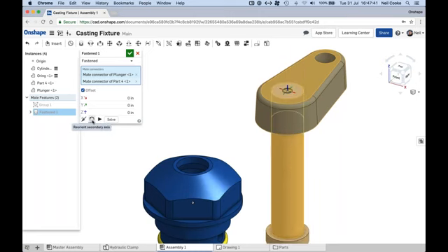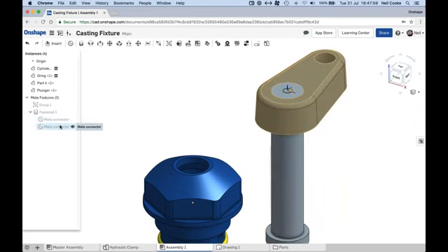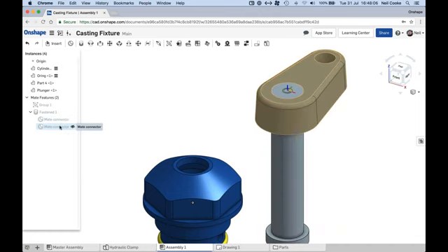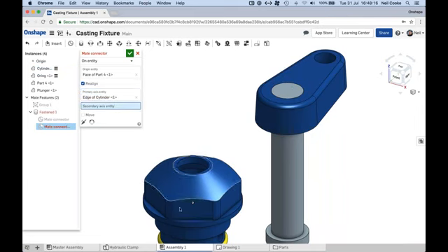The other things you can do here is you can flip it the opposite way around. You can also clock it around 90 degrees as well. The actual plunger is rotating there, which is why you can't see it moving, but you can see the mate connectors moving relative to each other. Another way to do it is if you expand a mate, you can see that it will actually show you the mate connectors that were used to generate this mate. So you can see the one that belongs to the plunger and the one that belongs to the mate connector. So if you wanted to put an offset in there, you can realign it to existing geometry. So, you could pick an edge over here. Oops, sorry, that should be the secondary axis.